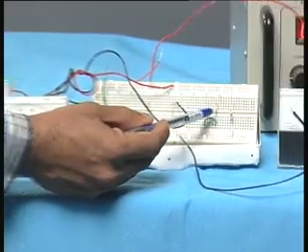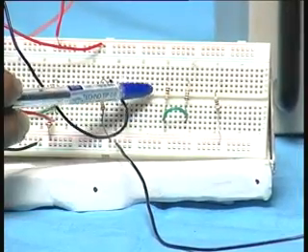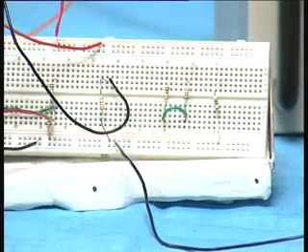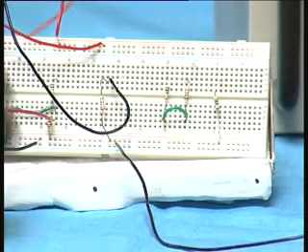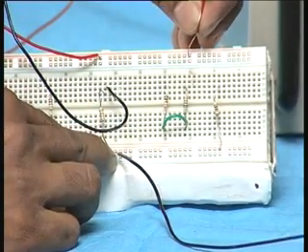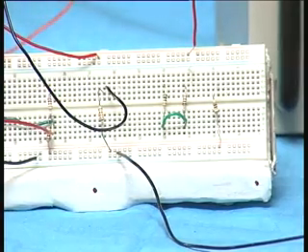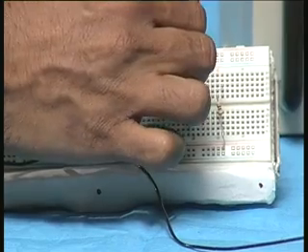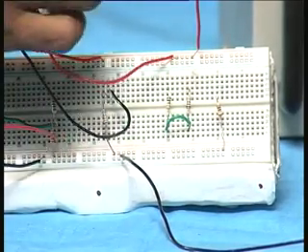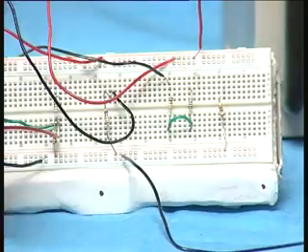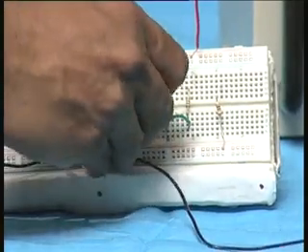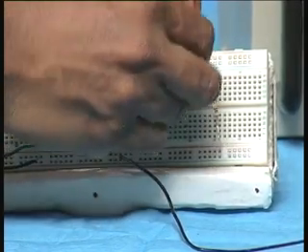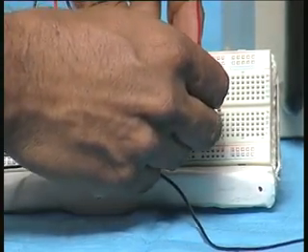You can see here I have two resistors, again they are 1000 ohms, 1K resistors. I have connected them together at the bottom, and the top one I will connect to the power supply quickly. So, I take the power supply, connect it at the top point, and I want to measure the current flowing through each of the resistors. Therefore, one end of the current meter I connect to the power supply, the other end I connect to one of the resistors. Similarly, I will take the other ammeter also, milliammeter, to the second resistor.